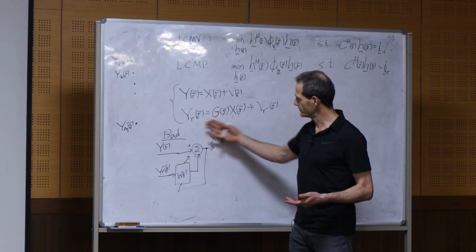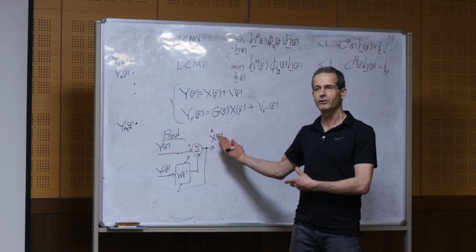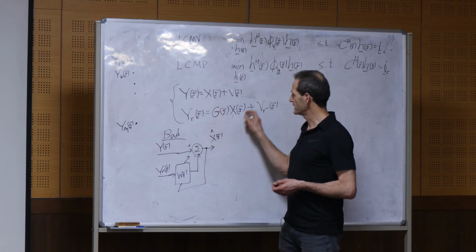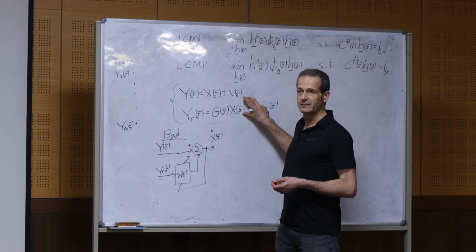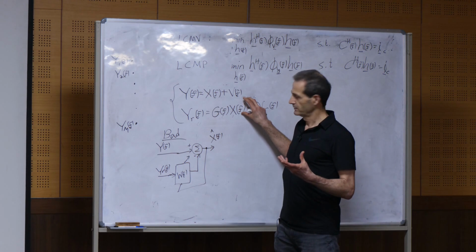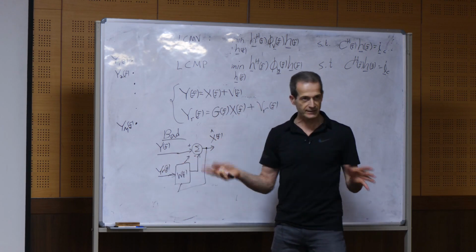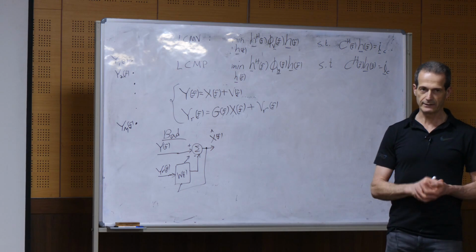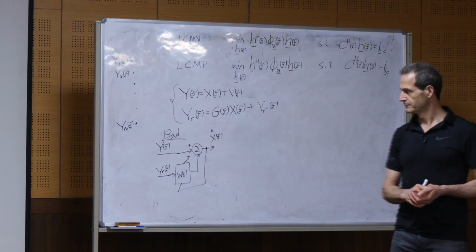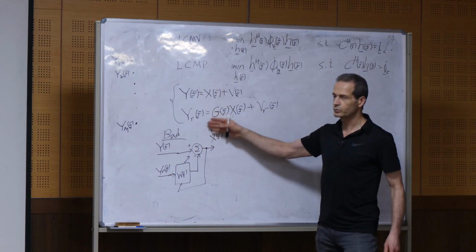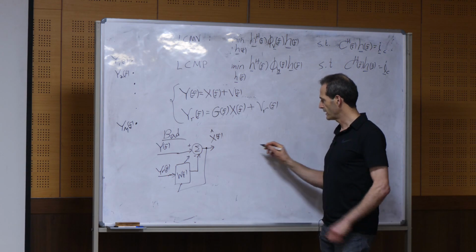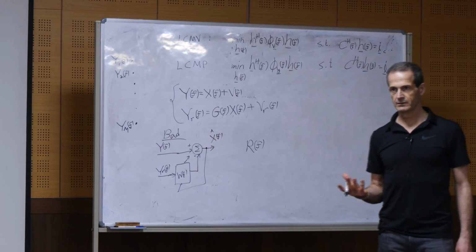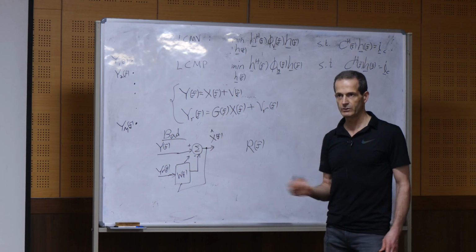So we know the problem that we solved before. So let's try, instead of solving this problem, to come to the problem we solved before with the adaptive filter. So what do we need to do? Here we have a reference channel with some desired signal. What we need to do is create a reference channel without desired signal, right? And then for the problem that we solved before, we know the solution. How do we do that? Okay, so from these two, do you agree that we can create a reference channel, RF, that doesn't contain the desired source? How do we do that?